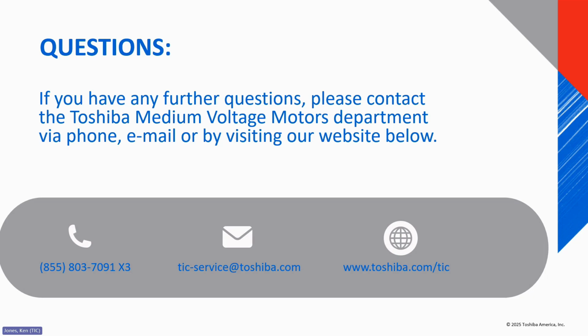Are secondary resistor control systems the best solution for wound rotor induction machines? There are options available based on the current. The larger the machine, at some point it becomes not cost effective to use resistors and contactors. When those systems basically come together, sometimes it's better to go to a liquid resistor package.